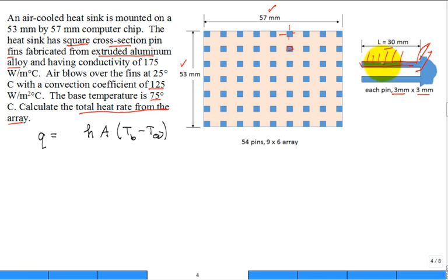And so the temperature's dropping as I go out that fin. So I better have some parameter, and we're going to call that eta naught. What's eta naught? Overall efficiency. It could be close to 1. It could be 90%. It could be 80%.